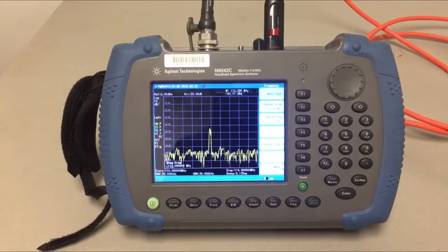Spectrum analyzers show the magnitude of a signal versus the frequency. We'll use it to find the frequency that our transmitter puts out by looking to see where there's a large spike in the magnitude of the signal. Where the spike occurs is the frequency output of the transmitter. We need to use a spectrum analyzer specifically because it has a very large range of frequency that'll definitely show the signal.